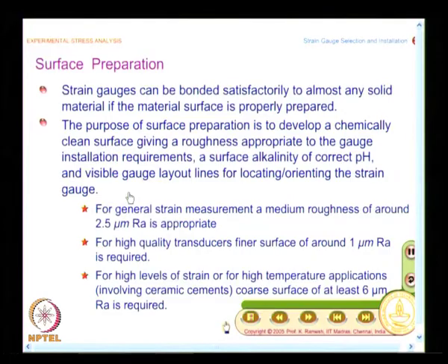See, this is very important. When you say in an actual structure, I want to measure strain, how I have pasted the strain gauge at the point of interest matters. So, I must align it appropriately, because a strain gauge essentially gives you the component of strain along the gauge length. If you have a misalignment, you will measure only strain along that direction, it cannot be interpreted to your direction, then you have to do a strain transformation law. For strain transformation law, you need to have pasted a strain rosette at the point of interest. So, strain gauge alignment is very crucial, it is not trivial.